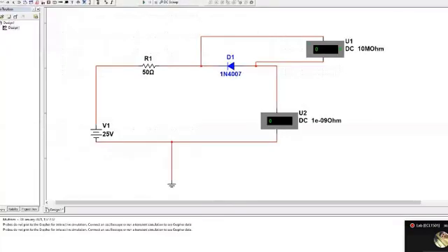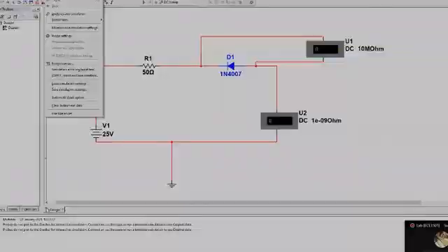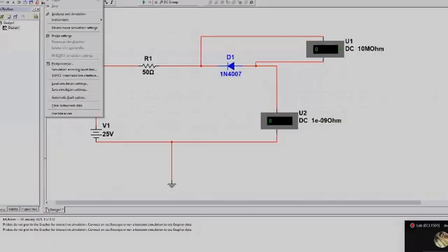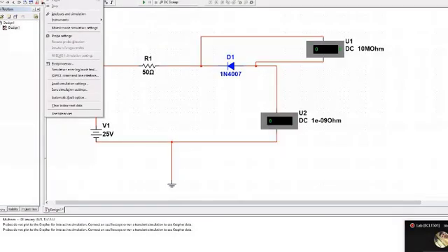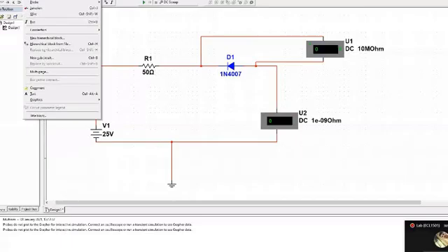Or else, if you do not see this DC sweep just beside the Simulate button, then you could go for the Simulate toolbar. Let me take that screenshot also. Simulate. Windows Shift S. Let me paste.